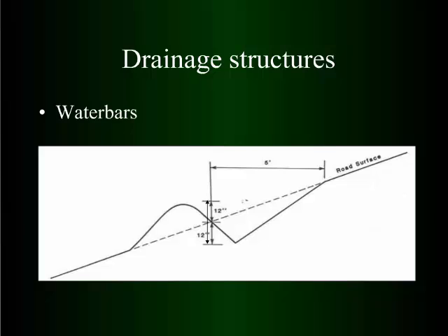Drainage structures. Assessing, we talked a little bit about water bars, and Lou showed some examples, and he did mention the clean out part. And the other part of it is when people put them in, they generally get the berm, but a lot of times they don't actually get it cut down into the subgrade. And it's pretty easy for that berm material to get knocked out of there. But if you actually notch it down into the subgrade, into the native ground a little bit, they tend to stay in a lot better.